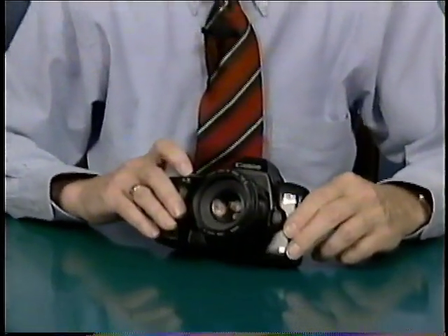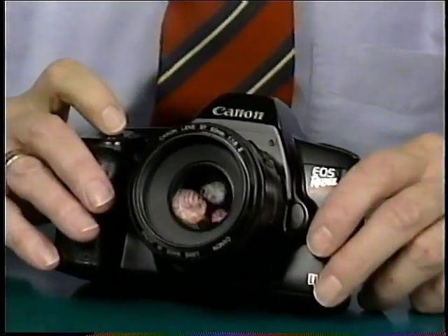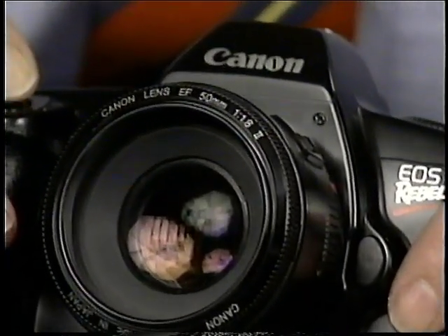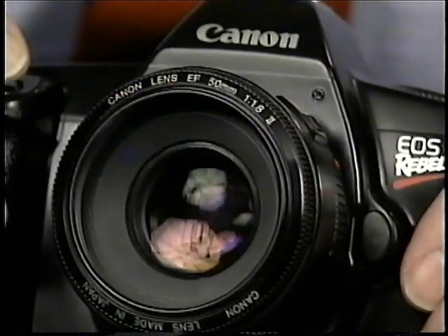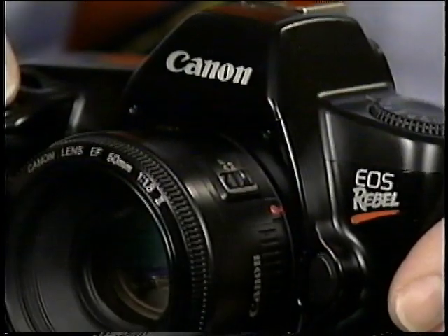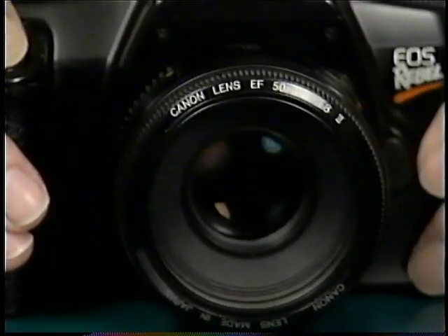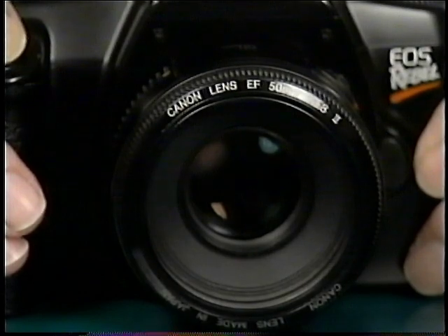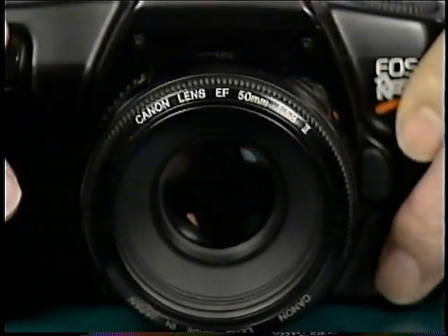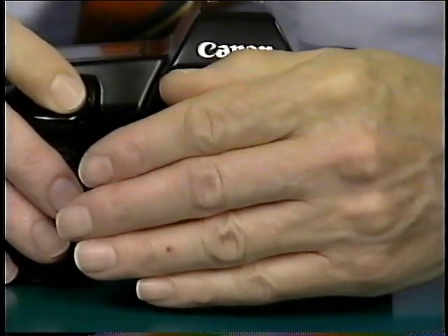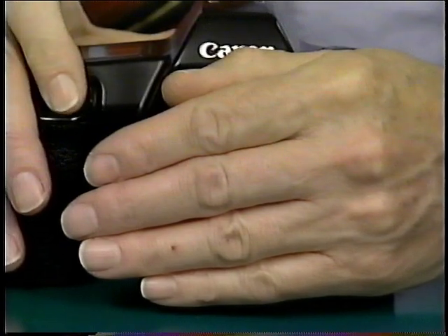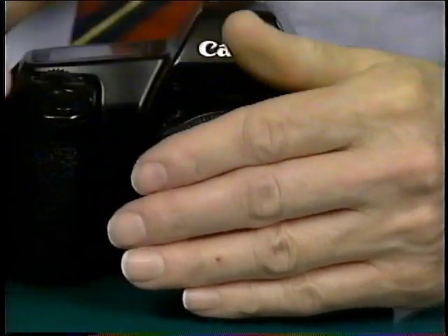Next, you'll need to make some exposures, first pointing to bright light and then to dim light, and just see what happens, particularly with the diaphragm. If we point towards some bright light and make some exposures, you can see the diaphragm is stopping down. And then if we point away to where it's darker, there's almost no stop down of the diaphragm, so that you know the exposure system is working. If we cover the lens, you should hear the shutter give a slow exposure, and you can hear the actual exposure slowing down.